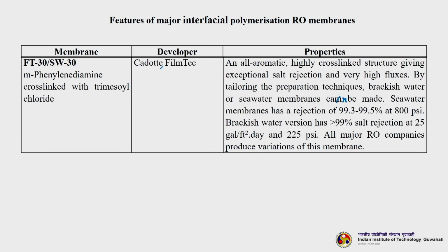The next membrane is FT30 and SW30. This is m-phenylene diamine cross linked with trimesoyl chloride. Cadotte at Filmtec developed this.